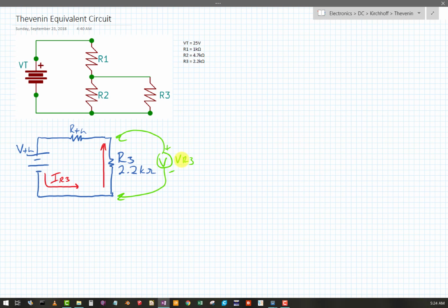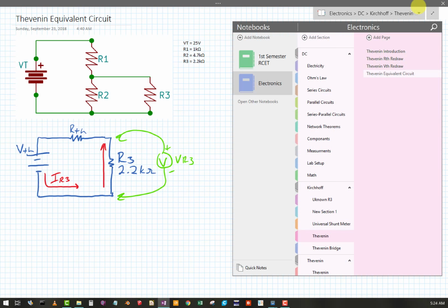There's a lot of things that I can figure out. Basically I can switch out any component in a complex network, and I don't have to solve the complex network. I only have to solve this little series circuit, which makes life easy when you're trying out several network configurations or loads or whatever it is that would go in your circuit between point A and B.